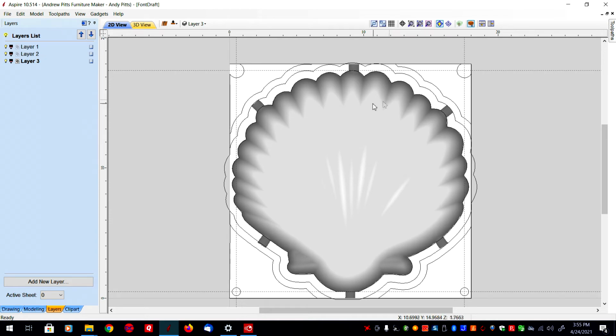I also found out that when I started cutting way back in here, I had to actually cut away a whole bunch of these upper corners because on the ShopBot desktop machine, there's a big plate that holds the spindle in place, and that plate was going to bash into this material.